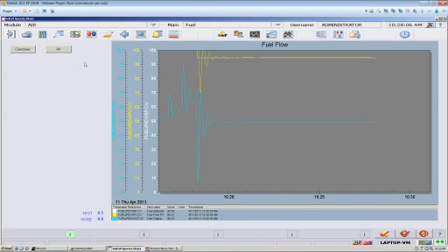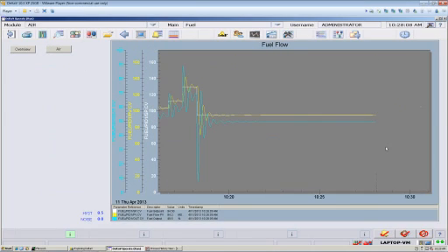Now let's move on to the fuel model. Same kind of thing. Before we tune this, I want to show how to use the Lambda process to diagnose the health of your plant. Now this is a simulator, so I can easily change the behavior of my valve, easily change the behavior of my process just with a few mouse clicks.